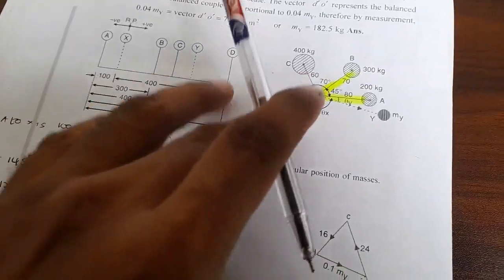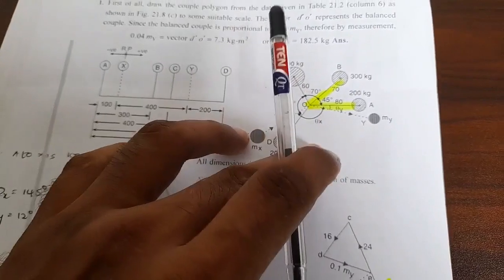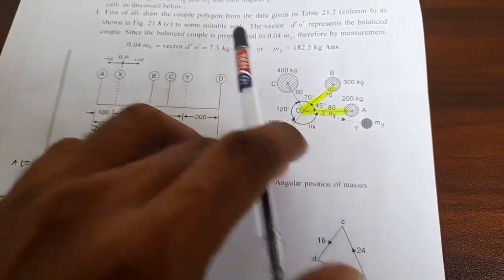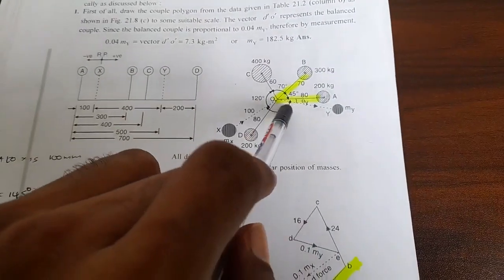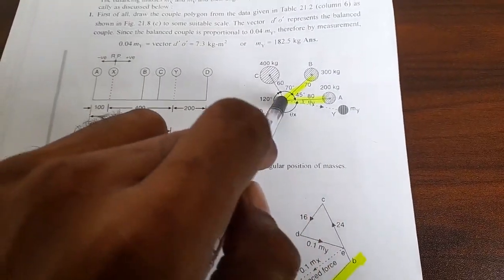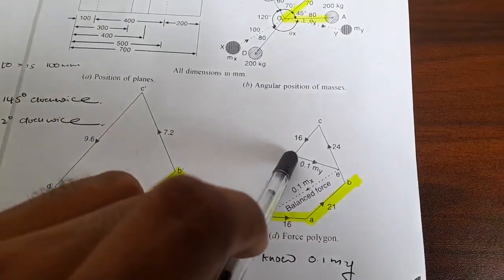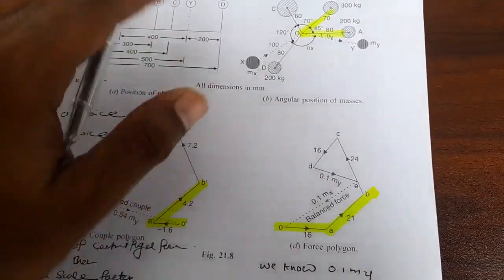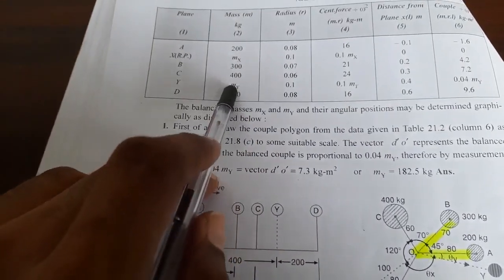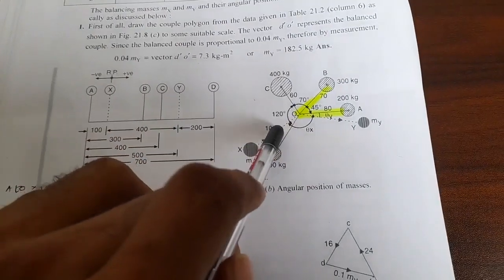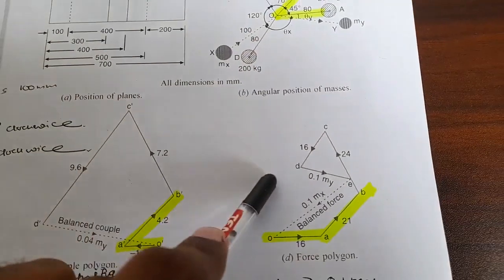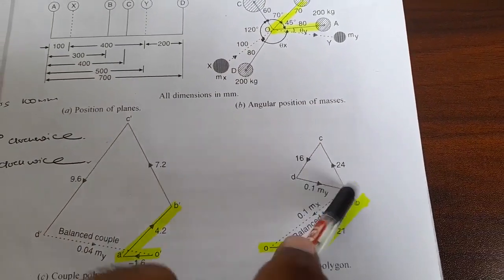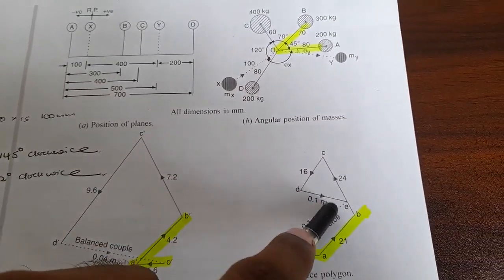Now this is the most important thing. You know the position for the mass My, and it is acting like that, going away from the center. Now this DE represents the centrifugal force because of the mass My. Just focus on it being directed away from the center. See, DE, right? Okay, so now it is done. We have completed all the forces up here.